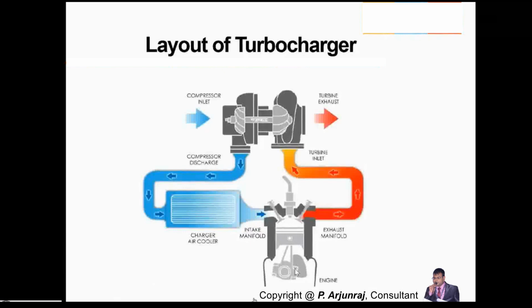The exhaust gas comes from the exhaust manifold, and before it goes to the atmosphere, since you are using the turbocharger, the exhaust gas will go to the turbine. When it goes to the turbine, the turbine rotates. I told you the turbine and compressor are connected by a shaft.